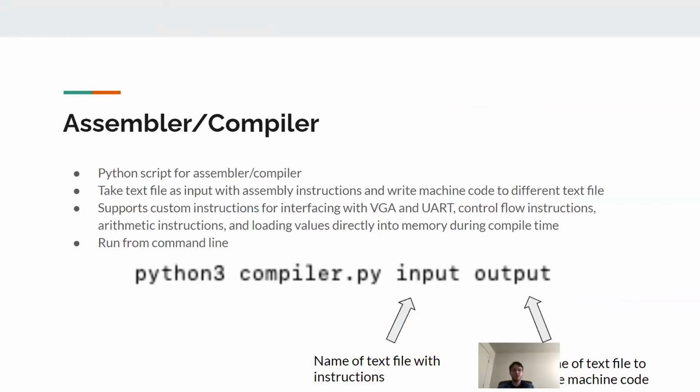So we have an assembler / compiler set up to generate code for our CPU. We have 2 separate files. One is our compiler, which will parse all of the assembly code, and it also supports if statements and comments. So it turns the if statements into the assembly code, removes all white space, and converts everything into the assembly instructions. So then the assembler can convert that neatly into machine code.